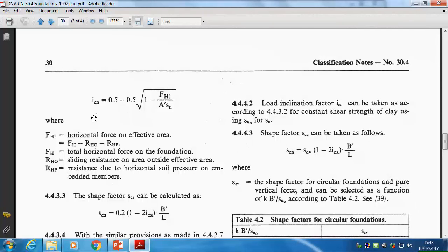And then plus P naught dashed. That allows for the depth of embedment, the surcharge provided as well, so that you're down for the length of the shear planes. But if you've got a structure on the seabed, that drops out, okay? So it really ends up, it's not a difficult equation. It looks harder than it actually is.